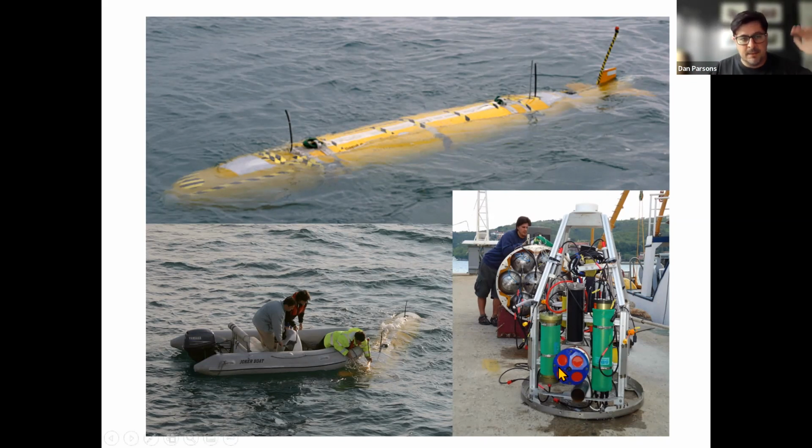but to measure the currents at the bottom of the Black Sea, if we measured from the surface, we'd get really poor resolution data, because these beams go out at an angle, and as you get further and further away towards the seafloor in 100 meters of water depth, they're insonifying huge parts of the seafloor. What the submarine allowed us to do was get much closer to the channels and almost survey this submarine channel in the way in which you would a terrestrial river channel with a boat. So we programmed the Autosub to skim across the top of the channel and measure the flow velocities in a series of cross sections down through the system.